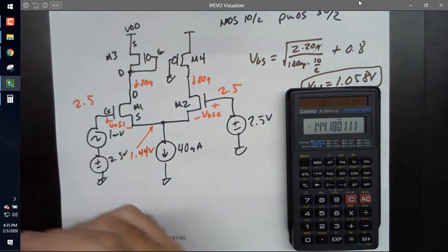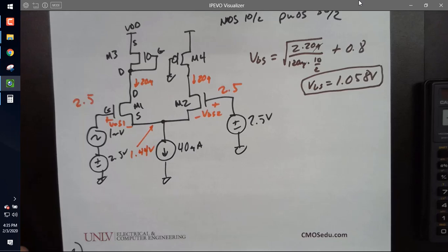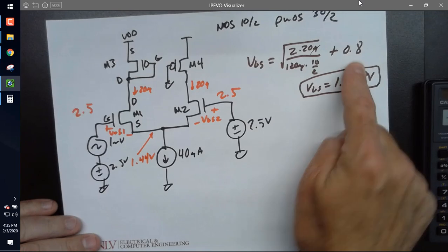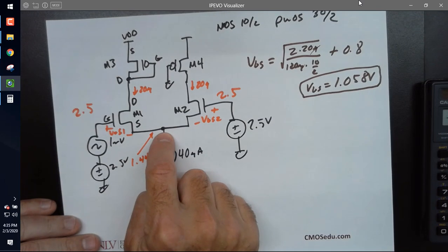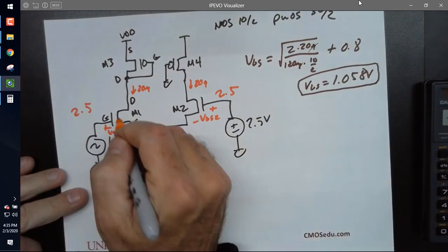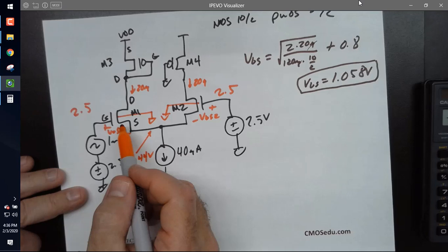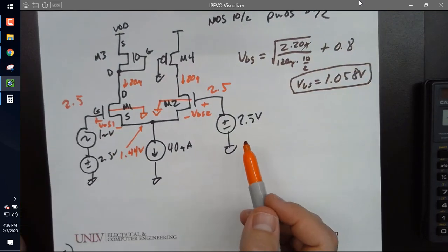And what was the body effect? People that took 421? Don't try to hide there, Cody. That means the threshold voltage goes up when the source and body aren't at the same potential. So instead of having 0.8, it would be like 1. So when you calculate and it says it's now 1.24, it's because the threshold voltage is not 0.8. The body steals charge, and I have to use a larger threshold voltage to turn it on.